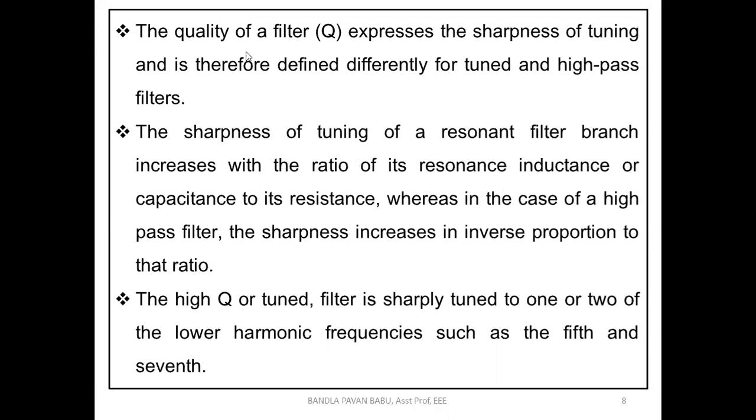Next, the quality of a filter. Q expresses the sharpness of tuning and is therefore defined differently for tuned and high pass filters. Before going for this tuning of filters, we must know why we go for tuning. If we prefer any particular type of filter which has the RLC components, and we vary the frequency, obviously the reactance is going to be varied. How are we going to perform this variable frequency? Let us consider the shunt connected FACTS components.